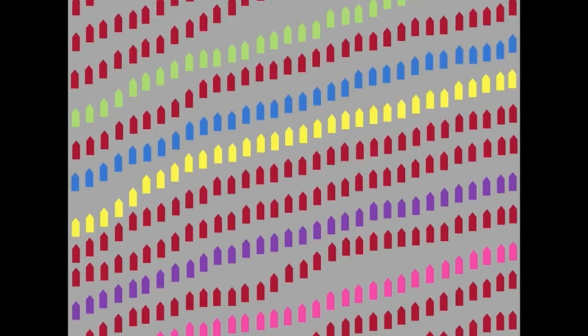Okay, so let's talk about how we use some of these basic measurements to create a time-space diagram. So consider that we take some aerial photographs of a particular highway at particular time increments. So this is the first aerial photo taken at time 1. And so in this case, you can see there are 6 vehicles on the road. So at successive time intervals, if we take a photo every second or every 5 seconds, we can start assembling little strips of aerial photographs until we obtain essentially a graphic that looks like this, that allows you to watch how each colored vehicle is moving over space and time.